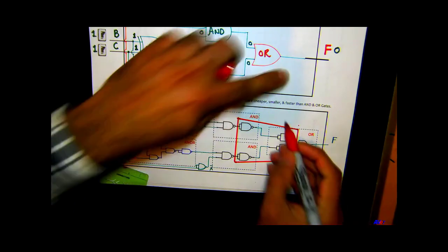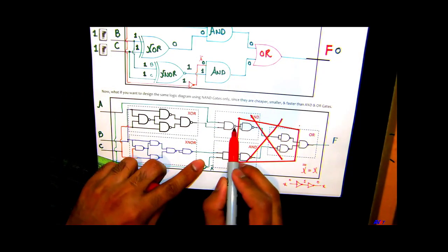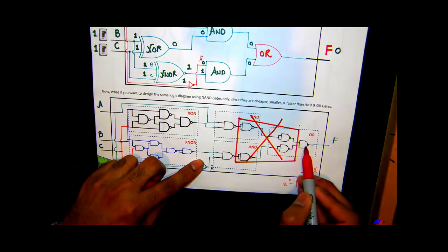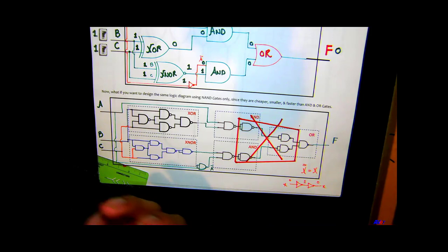what do you see in this part of the circuit? You basically see two inverters, right? And you can just delete this part of the circuit. You can just directly connect the output of this NAND gate to this NAND gate. You don't need these 4 NAND gates here because they are just acting as an inverter, right? And we don't need that. So this is pretty much it for this example. Does everybody understand what we have done here? Cool. Shall we move to the next problem, guys?